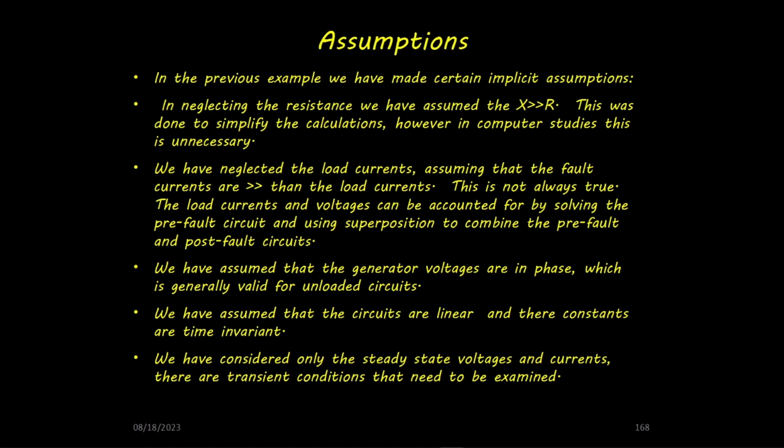We have assumed that the generator voltages are in phase, which is generally valid for unloaded circuits. We have assumed that the circuits are linear and their constants are time invariant. We have considered only the steady-state voltages and currents. There are transient conditions that need to be examined.